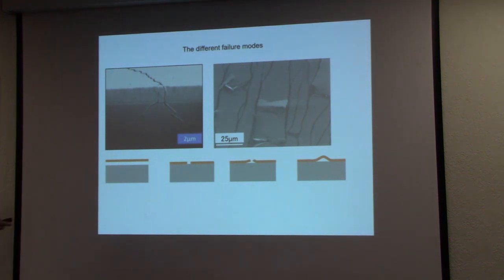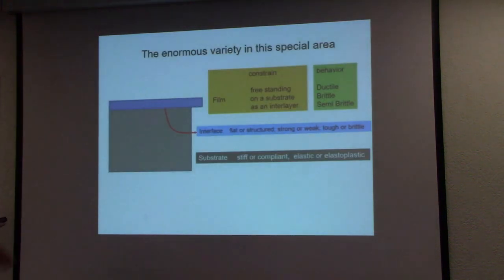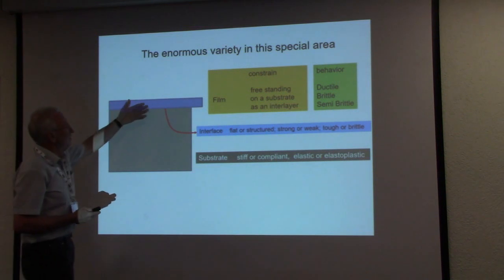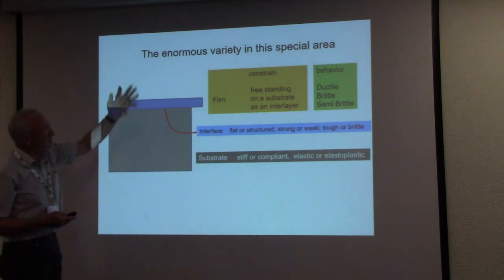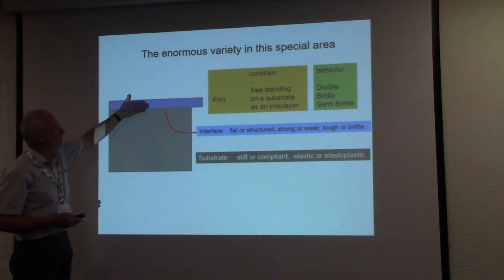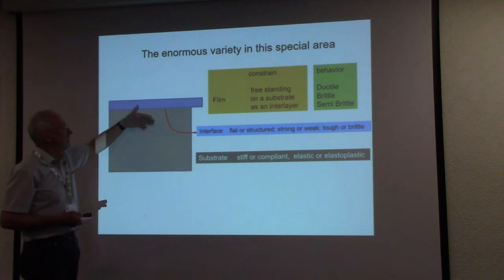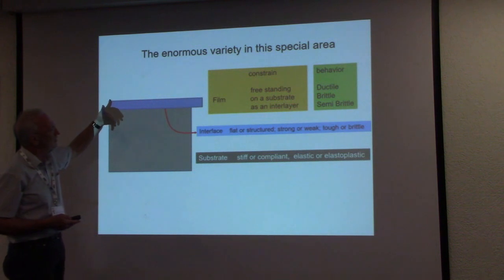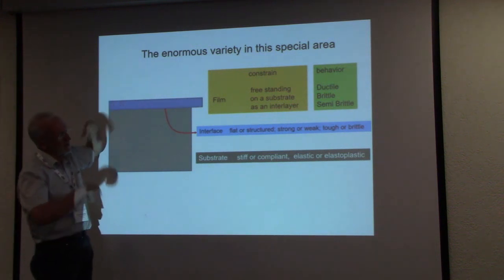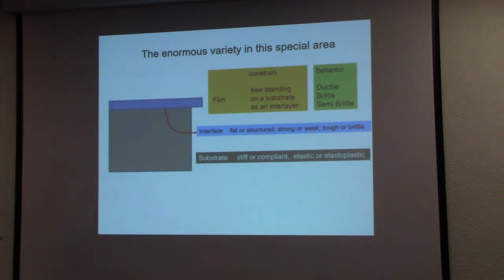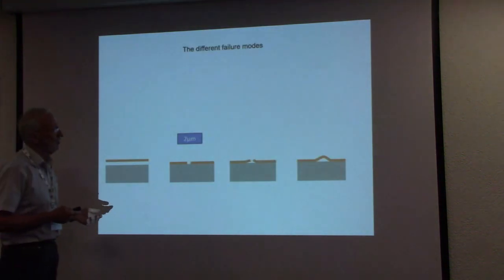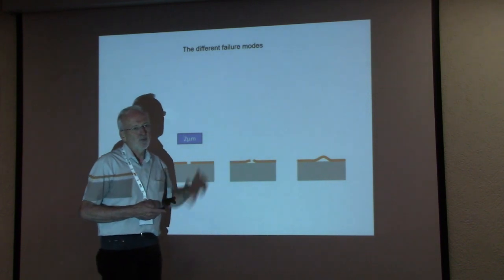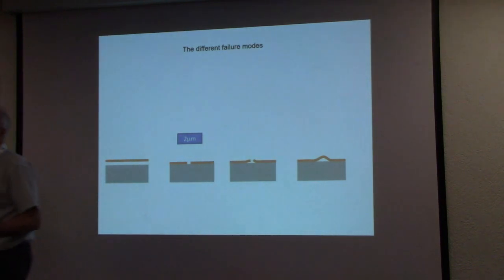And when we go to the fracture mechanics of these, then we have these differences, and we have this difference in the elastic and plastic properties of these two films, and we have the difference in the Poisson ratio and so on. Then always when we have, especially when we look to the interface fracture, we have always this mixed mode problem. And mixed mode problem itself is a mess